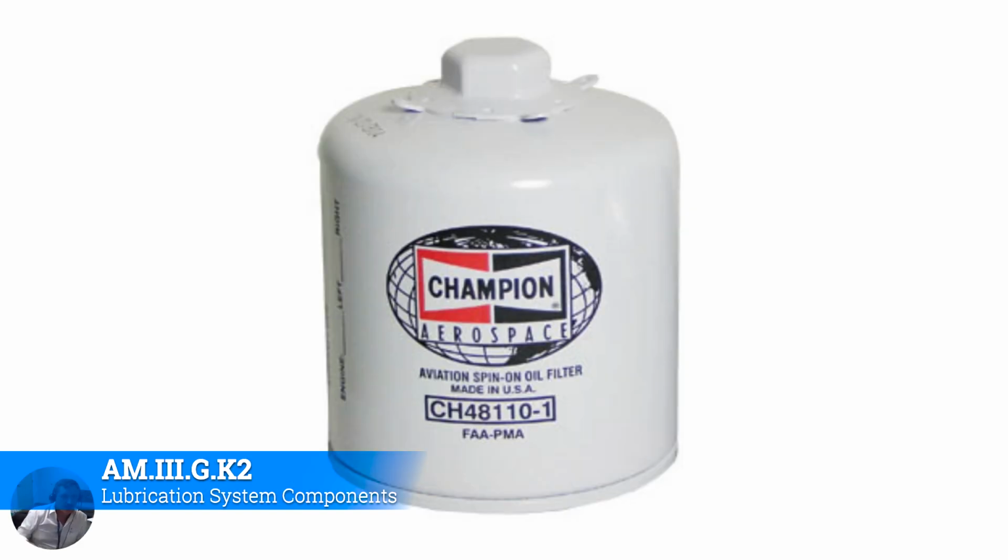Okay, so your aircraft engine oil system is just like your car's engine oil system. It has a filter on it. The engine oil filters on most aircraft engines are a little bit bigger, and they have to be safetied. You write the date and time on them whenever you install it, so it's the same idea, just a little bit higher fidelity on the quality of work that you're going to do and the depths to which you're going to dive in an oil change.